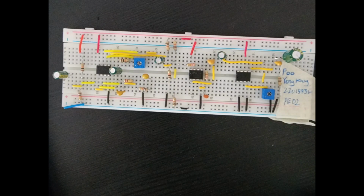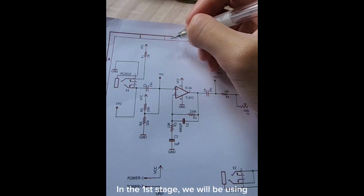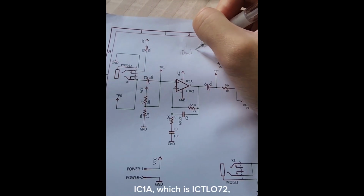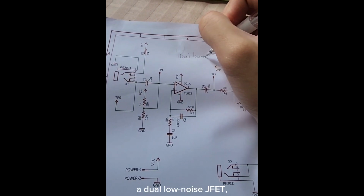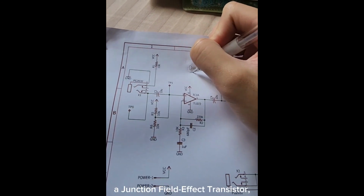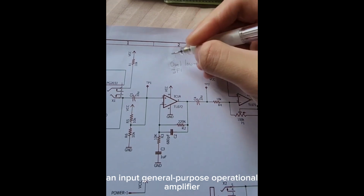This is my circuit. In the first stage, we will be using IC1A, which is TL072, a dual low noise JFET, a junction field effect transistor, input general purpose operational amplifier.